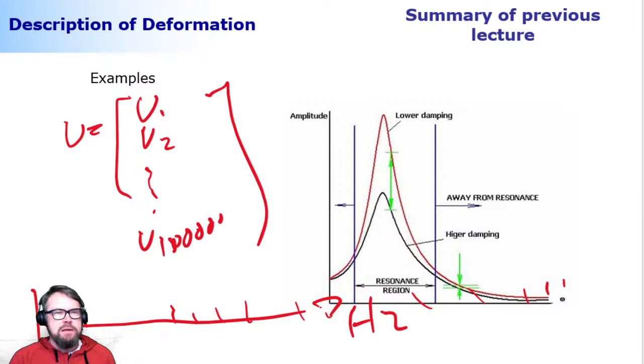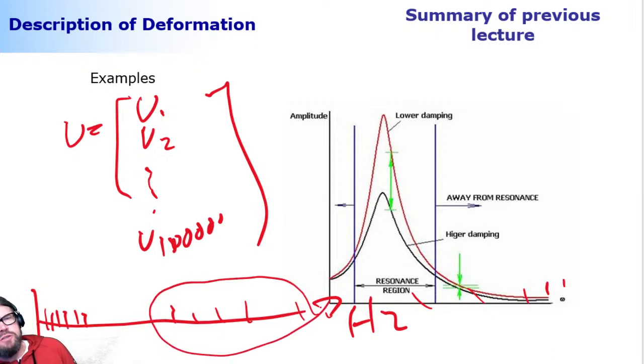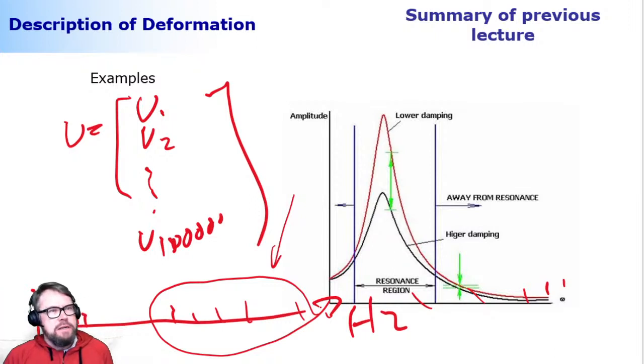And I know that my head is blocking the view. So if we think about these high frequencies, maybe they are not so important in terms of multi-body system dynamics, particularly because they correspond to deformation modes that are very complicated and probably contribute very little to overall performance. So we can ignore some of them, and there are even automated procedures to ignore them. This is exactly what we do in the model reduction technique.